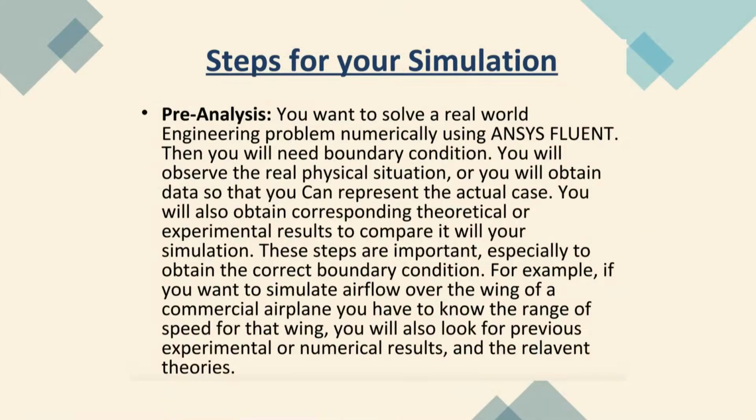So, the steps. First, the pre-analysis: you want to solve a real world engineering problem numerically using Ansys Fluent. Then you will need the boundary conditions. As I said, boundary conditions are very important. If your boundary conditions are not realistic, you will not get good results, because you are not solving the realistic condition. So, you have to deal with boundary conditions very accurately. Otherwise, your result is not physically correct. So, you observe the real physical situation, or you obtain data so that you can represent the actual case. You will also obtain the corresponding theoretical or experimental results, and then you can compare your results with them.